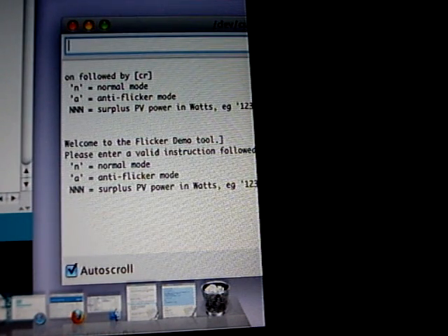The only reason that the voltage sensor is needed for this is to align with the mains cycle, so I know when to switch the triac on and off. The current sensor isn't used because all the currents are simulated, both for what we're generating from our PV and what we're sending out to the dump load.